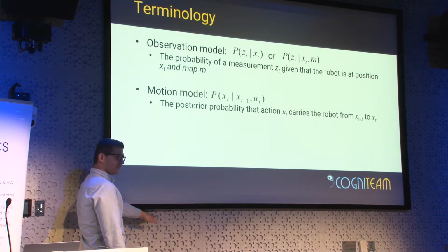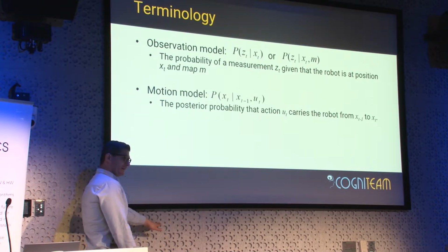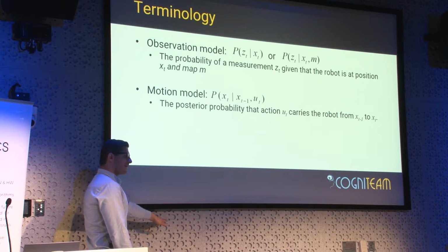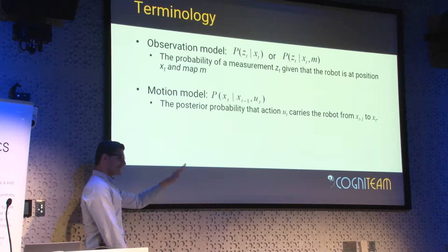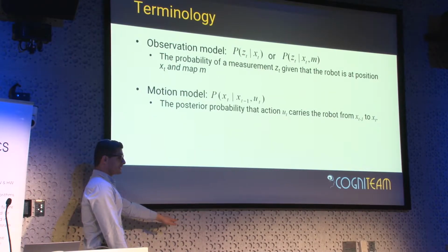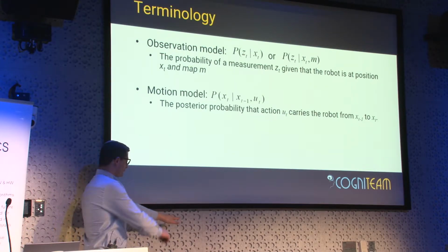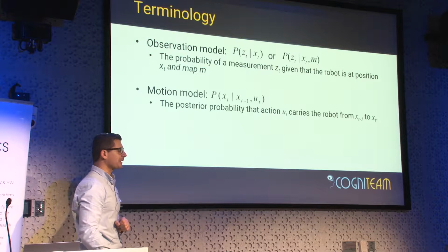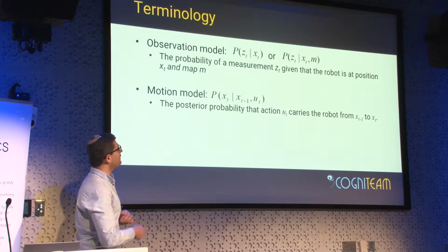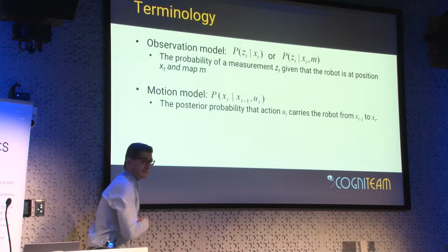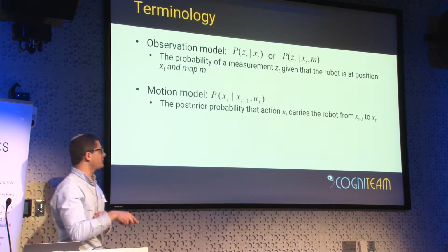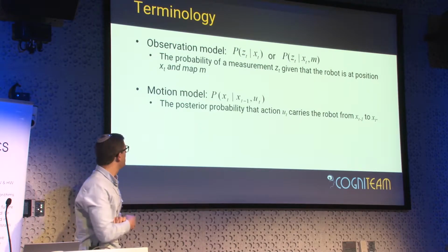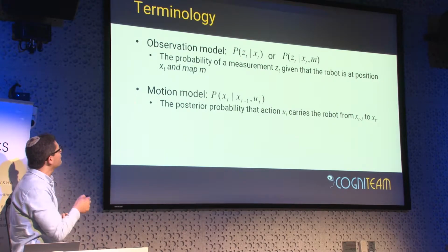In this situation, what is the probability? 1, because my sensor catches and touches an obstacle, okay? So what is the probability now if my sensor touches an obstacle? It's not 0, it's not 1, but it's quite close, because if I move a bit, it will be very close. So if I do a small search around the map, I find that my sensor can catch this obstacle. So this is P(zt | xt, m). What is the probability, when we are in location xt, and this is the map, to read zt. This is the observation model.